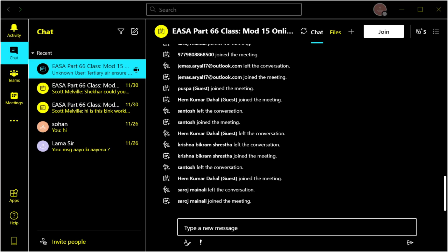Okay. So these are the high pressure ones. They can be reused. Some have a wire mesh support and some with a fibre. Unlike the fuel ones, which are pretty much once use only, these can be washed in an ultrasonic bath where it vibrates them very quickly at high frequency for about 3 minutes, and then they clean off with a solvent, and they get reused again. They might even have serial numbers for traceability for problems with engines.